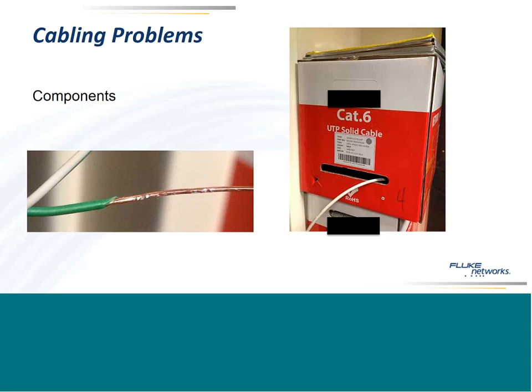But one of the ways to notice the difference is the fact that aluminum's a lot lighter than copper. So literally, we have had customers send us boxes where there are metal weights in the bottom of the box to make it as heavy as a copper box. So if you pick it up, you think you got a box of copper cabling, but you don't. And you remember I mentioned some of those other strange measurements like transverse conversion loss. Those can find things like copper-clad aluminum cable. Also, some of the resistance measurements can help you find that.